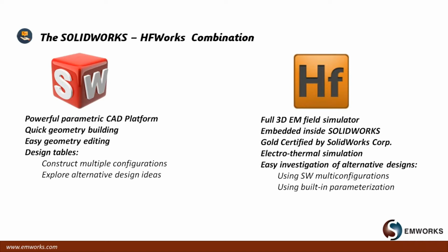So those are accessible. Although we'll not go over these things today specifically, you should know that it's available within the HFWorks package. And being embedded inside SOLIDWORKS, it also allows us to do the electromagnetic investigation of alternative designs in an efficient manner. So we can use the alternative configurations that we build inside SOLIDWORKS, or we can parameterize dimensions or other parameters in the simulation and explore our design space in that manner.